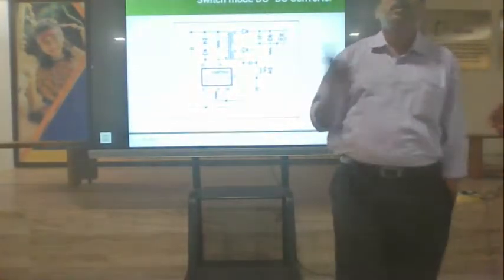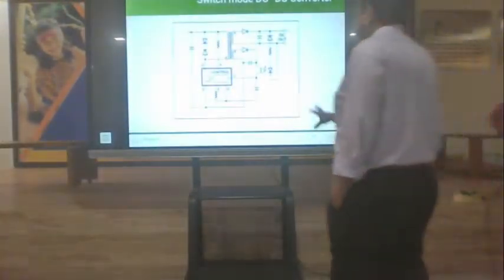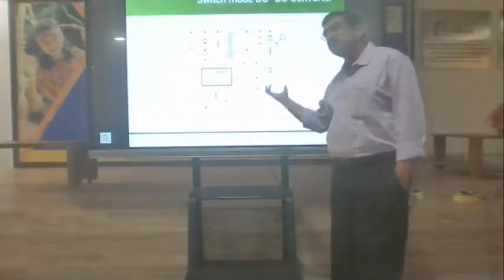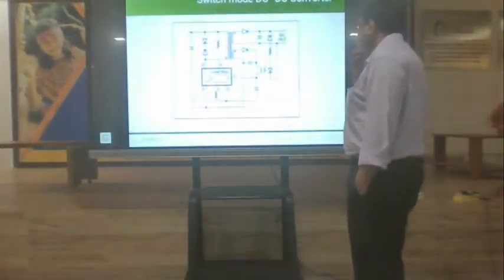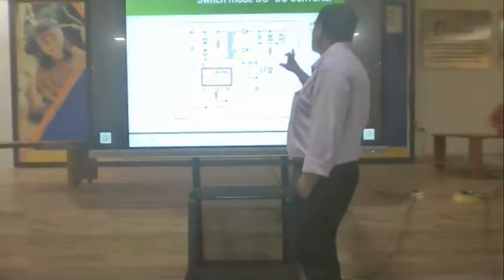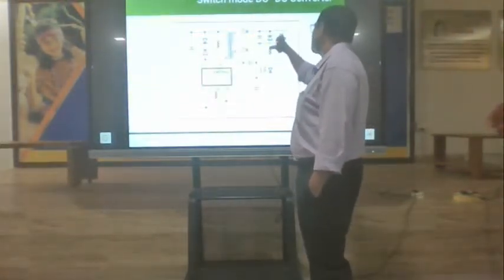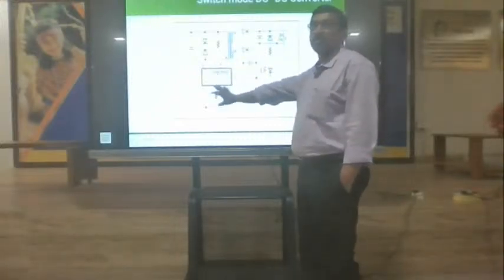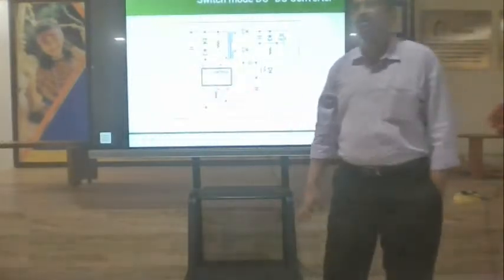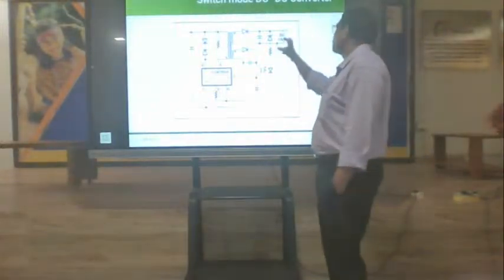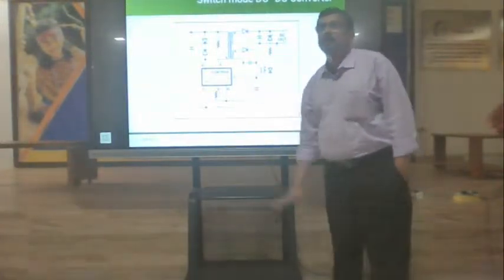Okay, this is how the DC-DC conversion works. This is the basic flyback conversion. There are other types of conversion which are similar. So what happens is this reference will be tracking the set voltage, and based on this, the controller will be changing the on and off time to maintain the output constant. This is how the DC-DC converter works.